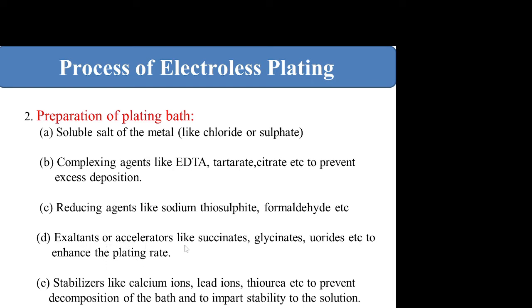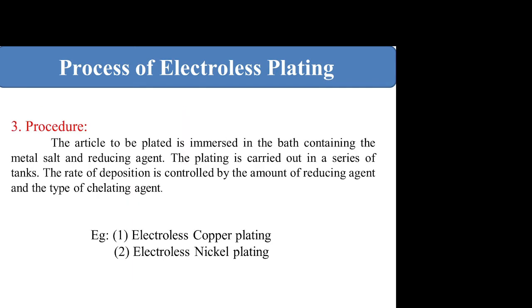This accelerator is applied on the surface of the substrate to be coated. Then stabilizers like calcium ions, lead ions, thiourea, etc. prevent decomposition of the bath to impart stability to the solution. Then buffer solutions like Rochelle salt and boric acid maintain the pH.